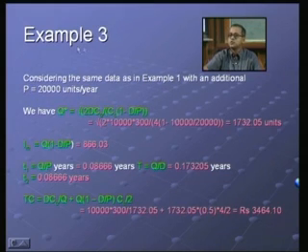So, Q star is root of 2 D C naught by Cc into 1 minus D by P, 2 into 10,000 into 300, C naught is 300, it is assumed to be the setup cost per setup, very similar to the ordering cost, rupees per setup 300, Cc is the same 4 into 1 minus D by P, 4 into 1 minus half, which is half. This gives us 1732.05 units.